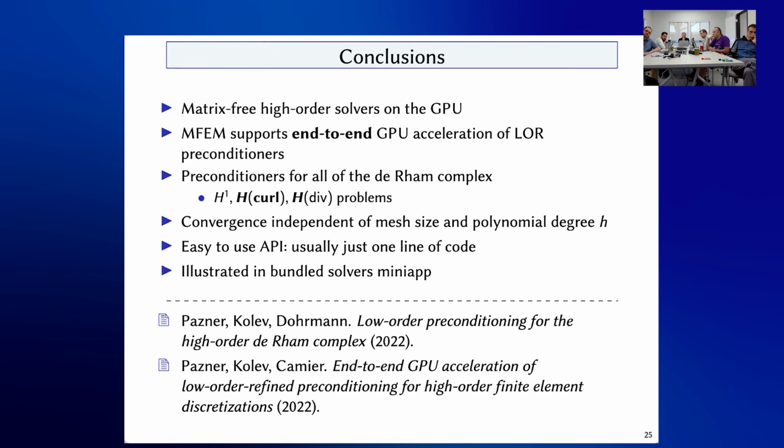So it will depend on the integration rule that you use for your higher order system. If you do something like SEM, spectral element method, then the integration points that you use for the higher order system are exactly the same points, and then the coefficient values will be exactly the same. If you do a more traditional finite element method where you use maybe some higher precision Gauss-Legendre rule, then yes, you're evaluating the coefficients at slightly different points. If your coefficient is well resolved and you have enough smoothness, the error should be small. In general, it's a preconditioner, and you're going to get some errors like that appearing in your spectral bounds, but it should not be a problem.